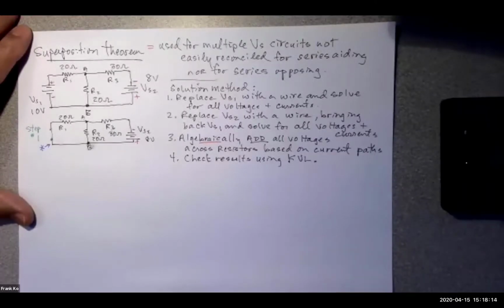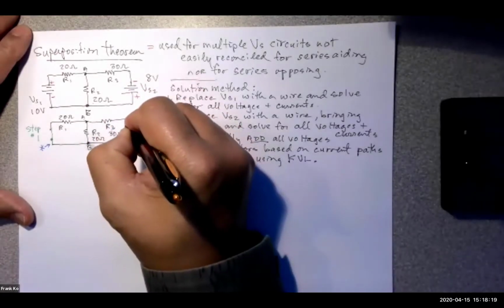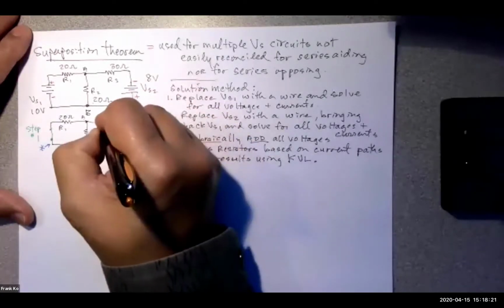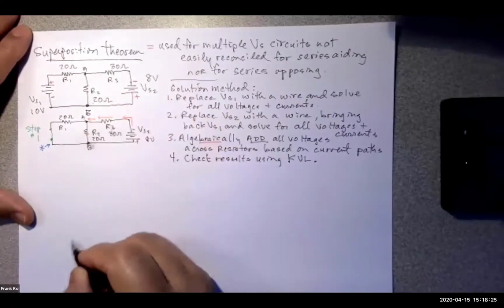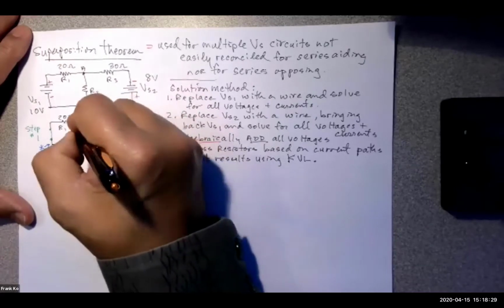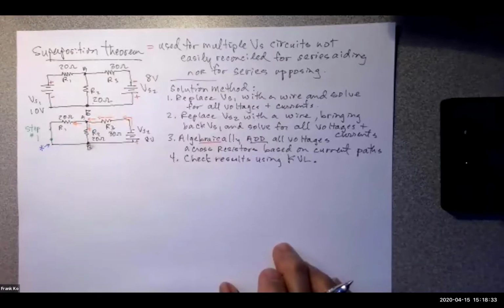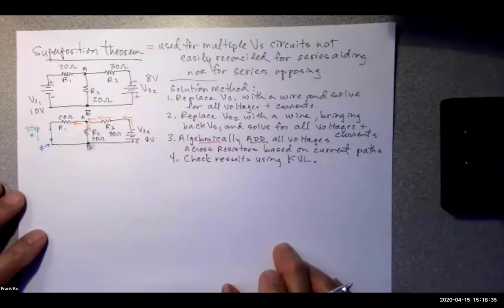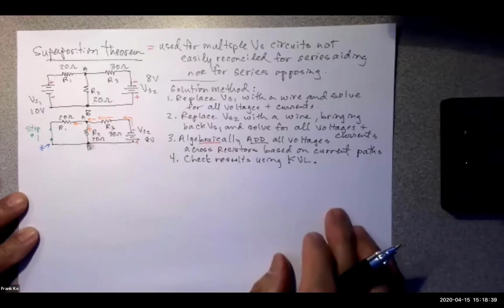Because if you remember, if we go to draw the arrows, here's the electricity flowing from the voltage source. Here's the electricity flowing through this resistor. Here's the electricity hitting node A. What happens at node A? The current split. So they are not in the same current path because the current split. And if there is a current split, they're not in series, because series means that they are in the same current path. R1 and R2 are in parallel.